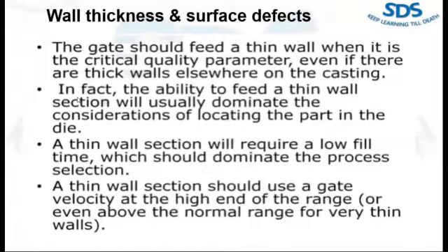So when you are designing your gates for a casting, you also have to divide the volume of the casting so that it gives the gate velocity as per your casting section, whether it has a low wall thickness or a high wall thickness. All right.